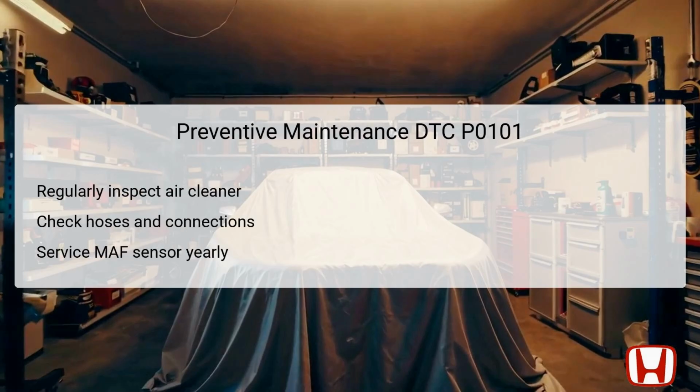Preventive maintenance is key to avoiding issues associated with the DTC P0101 error code. One fundamental step is to regularly inspect the air cleaner and replace it as needed to ensure unrestricted airflow into the engine. A clean air cleaner can prevent strain on the MAF sensor and avoid unnecessary errors.